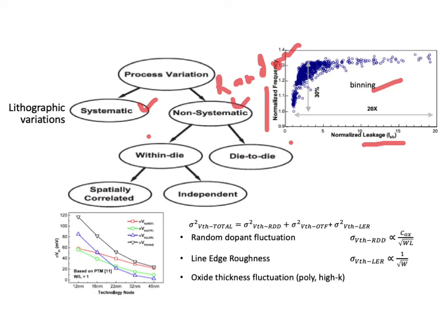And what's more surprising is that the leakage current varies much more broadly. There is a 20 times variation in the leakage current. That means the process variation for the exact same design will lead to one particular IC having 20 times the leakage current of another device. If you look at I²R losses, this translates to a 400 times difference in leakage power consumption.